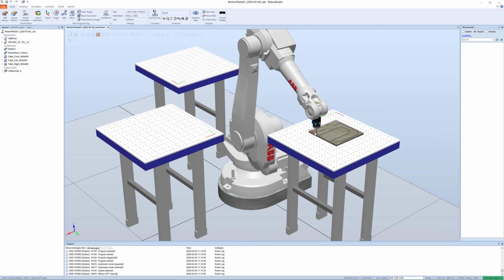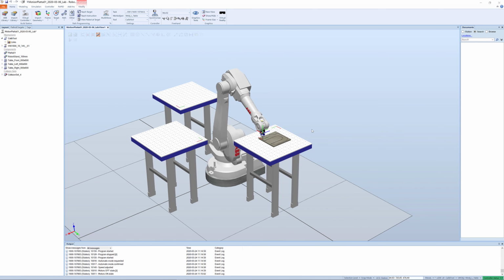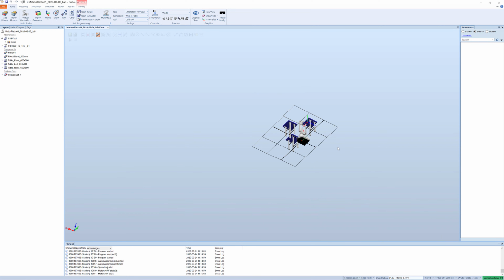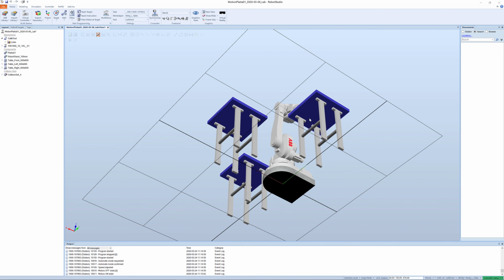If I right click here on the tool, right click, view center, I redefine what I am rotating around. If I click Control and the left mouse, I can pan around. If I use the middle mouse wheel, I can zoom in and out. If I use Control Shift left click, I can rotate around the viewpoint that I just selected. If I totally get lost somewhere, don't know where I am, I can right click View All. Then I am back more or less like this.